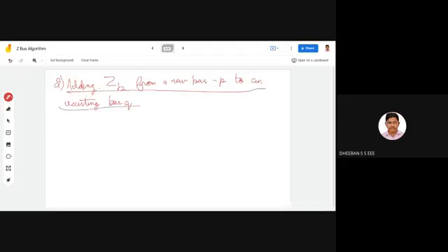Okay, so this we'll be seeing now. For this, the diagram goes like this. Again, you have to consider an N bus system. For this, we can consider this to be your bus Q. So it is an existing system. And over here you can consider your bus P. Okay, so the ZB lies in between these two. Okay, so it is adding ZB to an existing system.